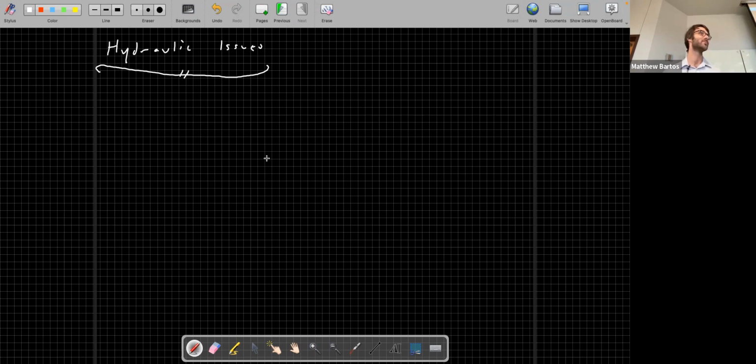Sometimes there are low areas where water collects, but there's no gutter. Right, so uphill, and it's kind of trapped in the flow. Great. So there's a specific type of curb inlet that's used to correct that, called a sump or sag inlet. So we'll have to think about any sags in the local drainage gradient.